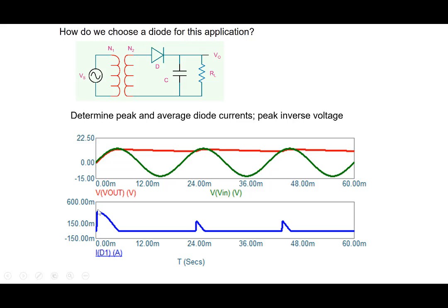The diode current has a very interesting waveform. Note that initially, if I start at t equal to 0 and I switch on my system, the capacitor is uncharged and the voltage starts from 0 and starts building up. The diode turns on. Note that it turns on here, and the capacitor starts charging. As the capacitor reaches its final value close to this, the diode current falls to 0 here. The capacitor is fully charged and the diode current falls to 0.